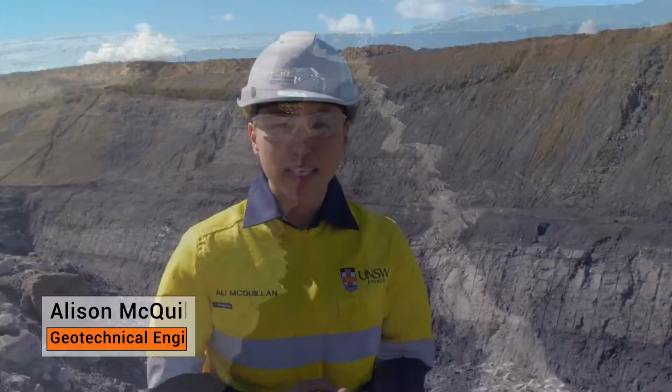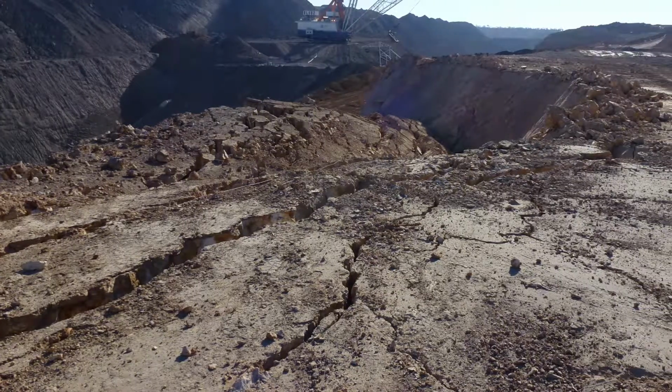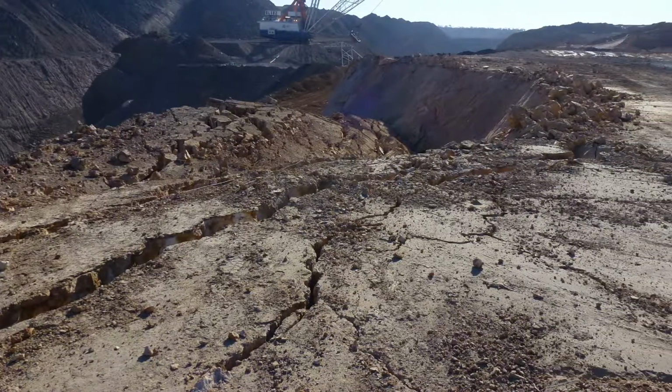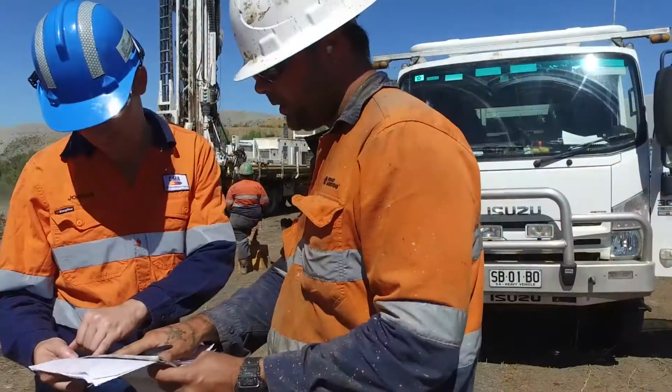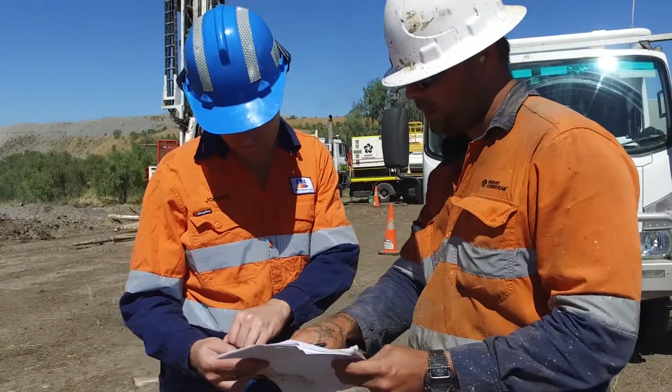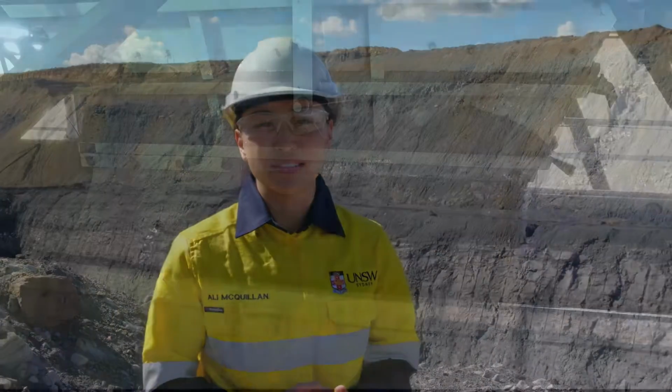Open-cut coal mines are dynamic environments. Coal mine workers must be familiar with their work environment at all times. Always remember, rocks fall down, so look up and look around. If you see any of the warning signs, notify your supervisor, the open-cut examiner, or the geotechnical contact on site. Follow all instructions given by your supervisor and minimise your exposure time in delineated geotechnical hazard zones.